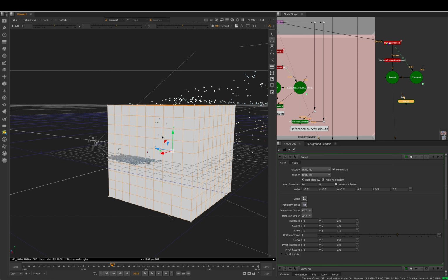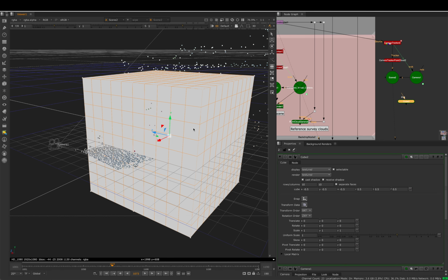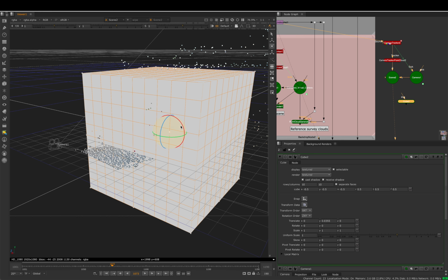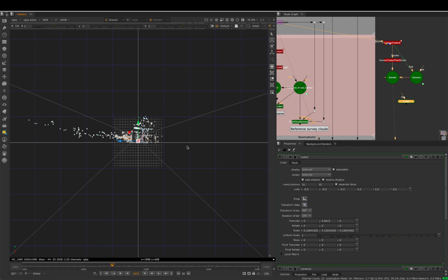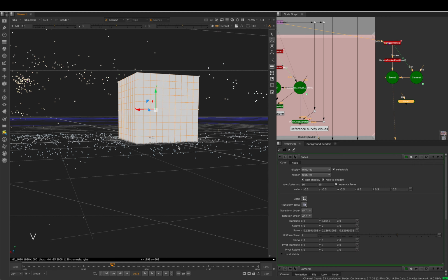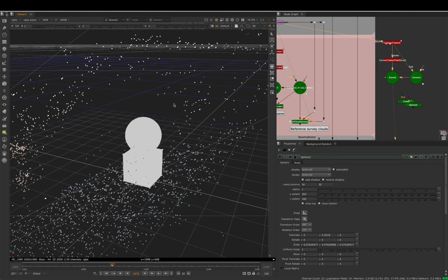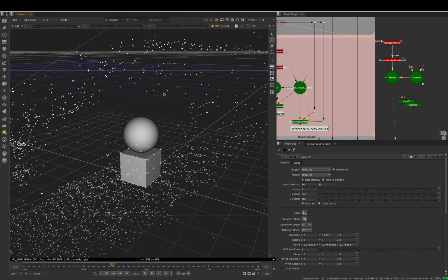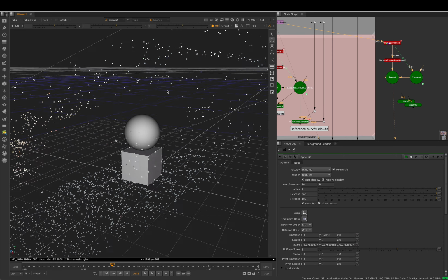By default, it's going to be huge, but if you press W, you can bring up the translation gizmo, E for rotation, R for scaling up and down. You can switch to different views, Z, X, C, V, and go back to the perspective. If you want, you can switch on the light, so you can better visualize your geometries in the scene.